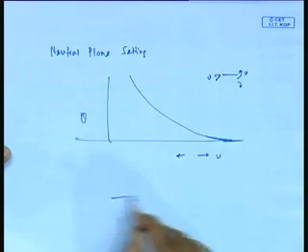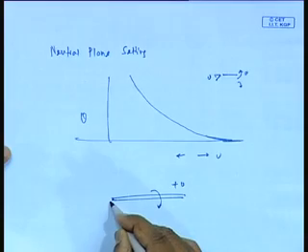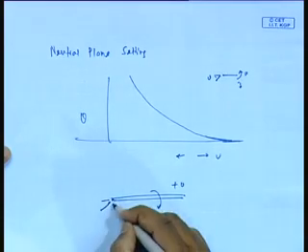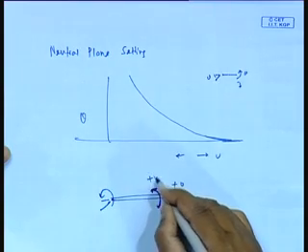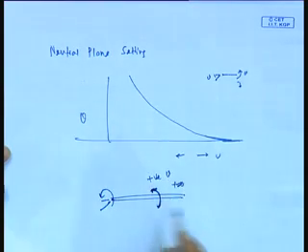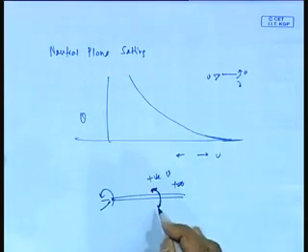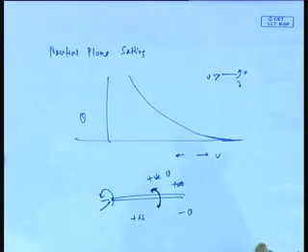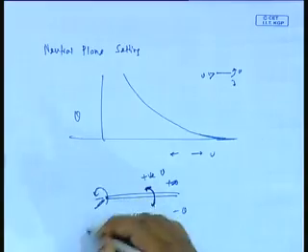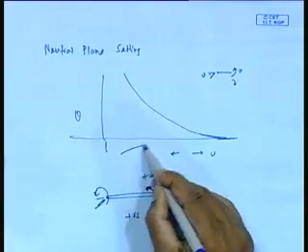What I mean is, if this side is positive theta, and now I turn this plane, this is negative, this is positive. So nose up is positive, and if I want nose down, for negative theta, I need to give positive delta s. Delta s is this one, the positive delta s. So if this is delta s, rather we call it theta.